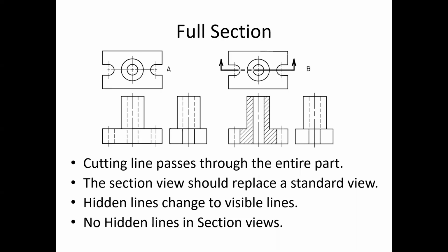So how hard is that rule? I want you to leave here wanting to not put hidden lines in your drawing views. Okay. And you go and you submit a section view for review when you go to work and your manager says, we want to show some hidden lines here. You put the hidden lines here. I mean, really, it's that simple. For the stuff that you're going to turn in to me, unless there's a specific note saying, in this section view include hidden lines, no hidden lines. And I don't think I have that note in any assignments.